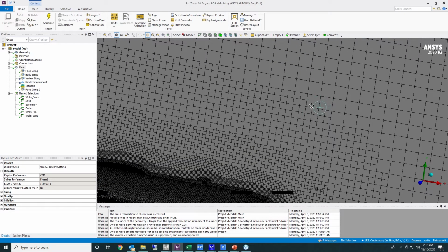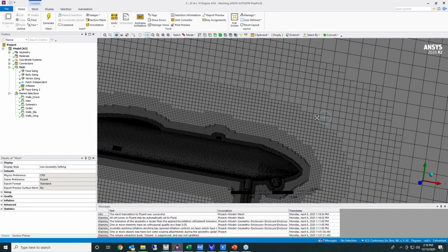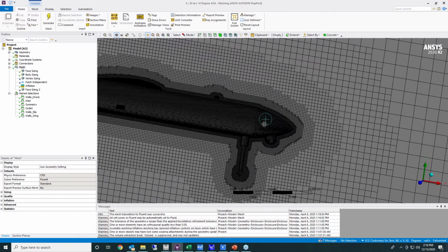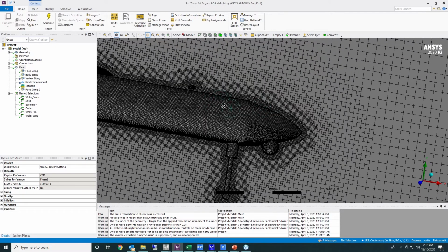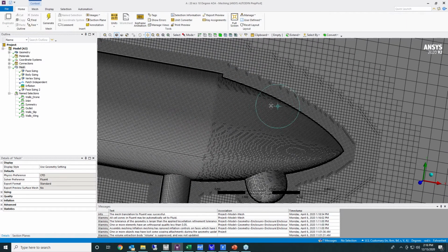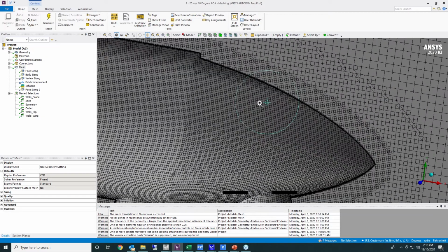So this one mesh block right here, that face gets cut into actually 4 different smaller blocks. And as I get closer, this mesh cell gets cut into 4 blocks. So you cut, that's why it's called cut cell meshing. So it can quickly go from a very coarse mesh out here in the free stream to a very fine mesh down here along the body where I'm going to have gradients. I'm going to have gradients of velocity that go from free stream velocity down to 0 on the walls because these are no slip walls. And I'm also going to have gradients of pressure. And so I need to capture those.